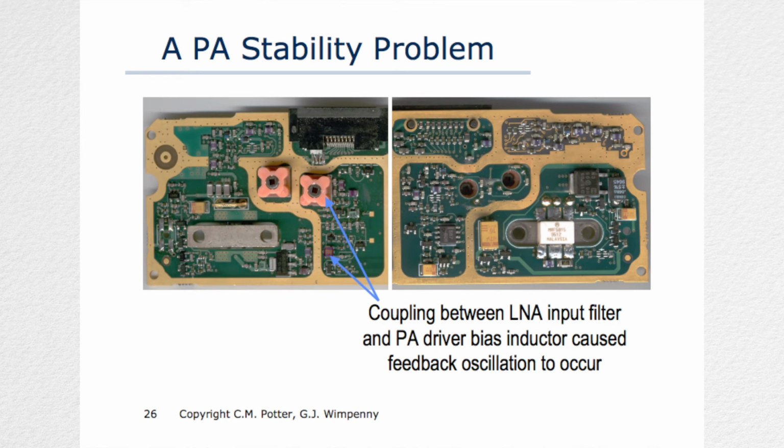My second example is of a power amplifier that was used in a VHF product for data communications. So there's actually a view of both sides of a circuit board here. It eventually goes into a sort of a metal clamshell which provides some screening between various different pockets. So this business of preparing the surface area with little compartments that can be used to mount a shielding arrangement.